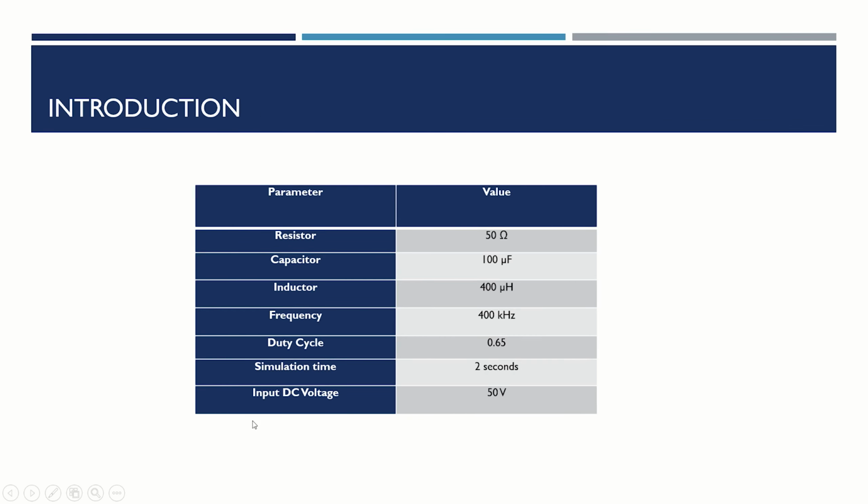These are the parameters that we use in our project. So resistor 50 ohm, capacitor 100 microfarad, inductor 400 microhenry. Frequency, we have selected 400 kilohertz, and duty cycle we set at 0.65.